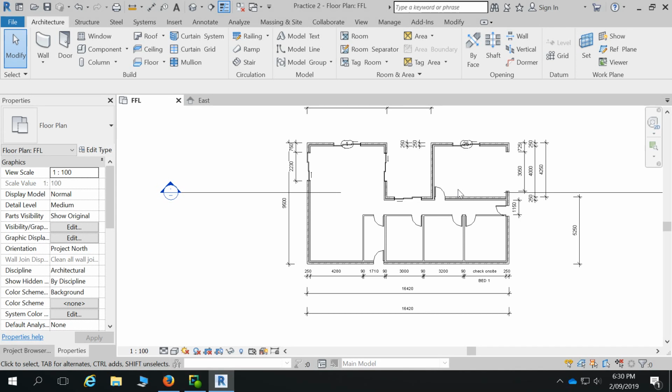Who the manufacturer is, how much they cost, what type of glazing, what type of framing is it? Is it aluminium, timber, whatever? If it's a door, is it a painted finish? Is it, whatever it is? So there's lots of extra information we can put by creating a schedule, and all we need to do is have a number so that someone can see door number 1 is this, this, this, and this. Otherwise, we're going to have a heap of information on our drawing that we've got to try to fit in next to each window or door.